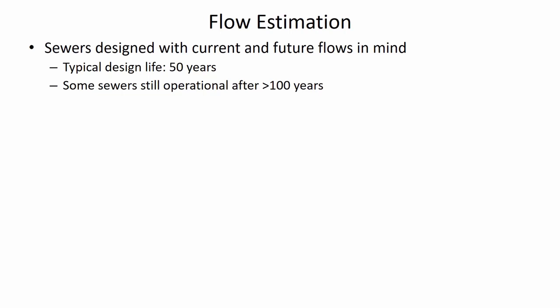And they never expected that there would be so much paved area, because when you pave over the land, it reduces the ability of rainwater to infiltrate down into the soil. And so then that increases the amount of runoff there is. And so all of the water that's coming from sidewalks, from roof drains, from roadway surfaces, all of that land area, if you look down on a map where it used to be plants and trees that would help promote infiltration into the soil, nowadays those are surfaces that don't allow any infiltration, so there's more water going into these collection networks than ever before. And so the pipe size was much too small. They weren't thinking in terms of what would be in the future.